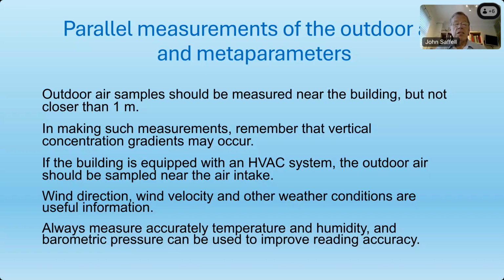And it's always sensible to measure accurately temperature and humidity and the barometric pressure, which can be used to improve reading accuracy. Barometric pressure corrects the straightforward thermodynamics of measuring particles in a fixed volume, which is what we do with NDIR.